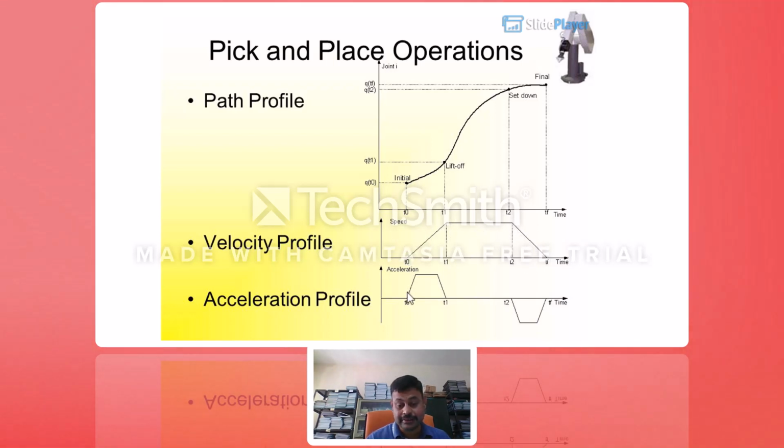Whereas for acceleration, whenever speed variation is there, it will count. So you will get an acceleration. It is increasing, then reaching one particular acceleration. That means constant velocity, constant speed. Wherever speed is constant, acceleration will be zero. Then again, you will get a down movement. A down movement is always called a deceleration. So again, same thing. This is the acceleration profile for the pick and place operation. Pick and place means the application I clearly described, the parts moving from one place to another place.